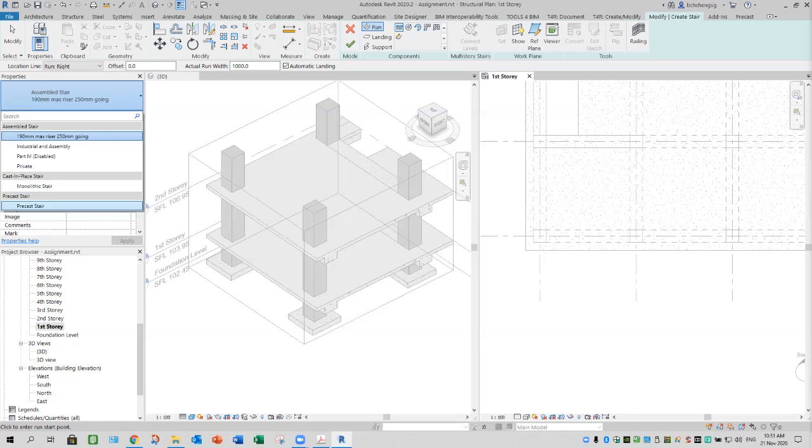Precast, the landing for the staircase will reach exactly level to level. But for cast in place, the last landing is not flush, it's one step lower, because cast in place takes the last step, the landing, as one tread count or one riser count.